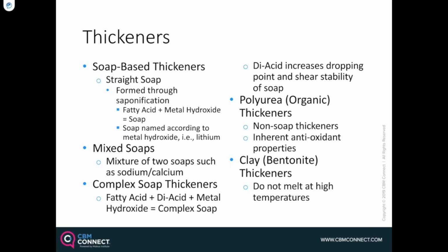When you look at the technical data for most greases, it's going to have a dropping point on it. The dropping point can be pretty high. It could be 450 to 550 degrees F. That doesn't mean the grease can go that high, but that's under no mechanical shear. That's the temperature at which the first drop of oil comes out, and that's the dropping point. Clay bentone greases do not give up their oil just due to high temperature, so clay greases are frequently used at higher temperatures.